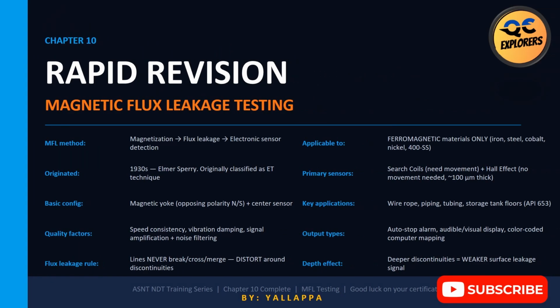We've reached the end of Chapter 10. Let's finish with rapid revision. Repeat these mentally. MFL method. Magnetization, flux leakage, sensor detection. Applicable materials. Ferromagnetic only. Origin. 1930s, Elmer Sperry. Primary sensors. Search coil and Hall effect. Basic configuration. Magnetic yoke with opposing polarity magnets and center sensor.